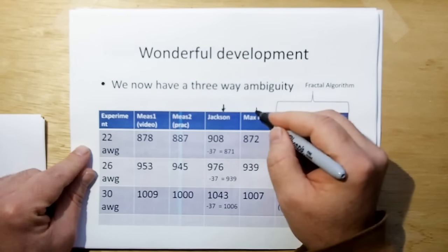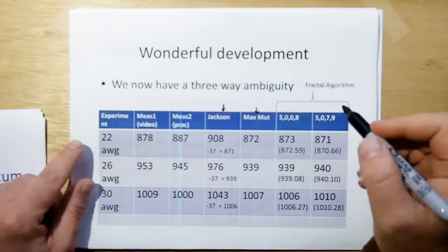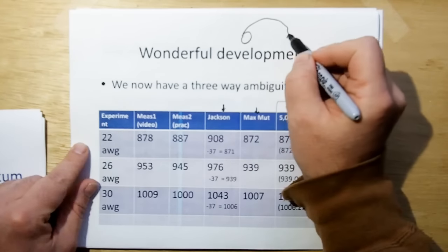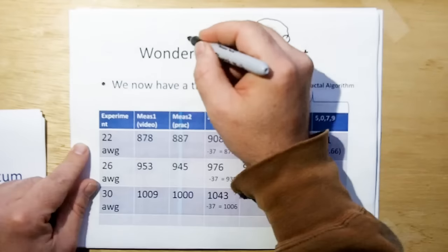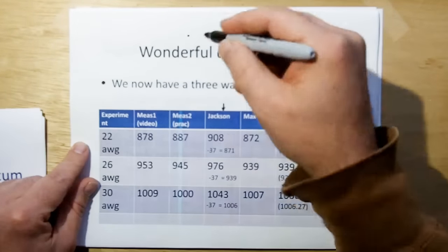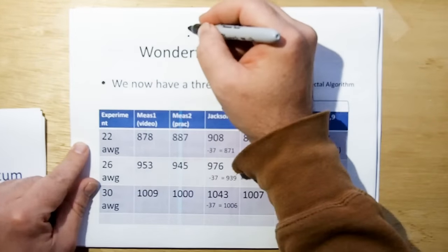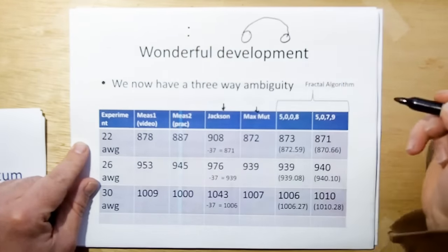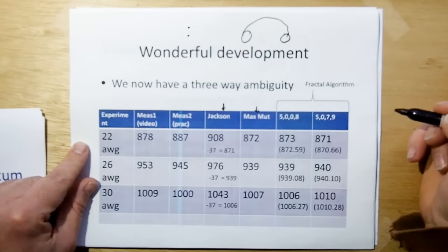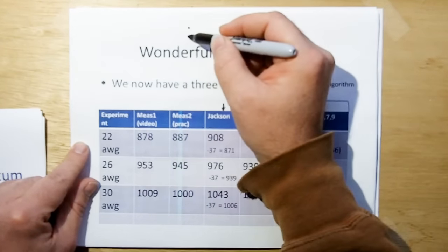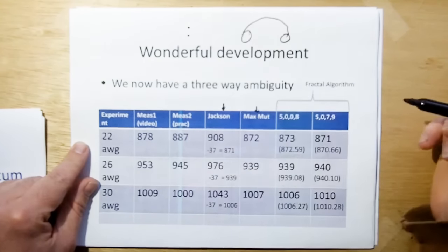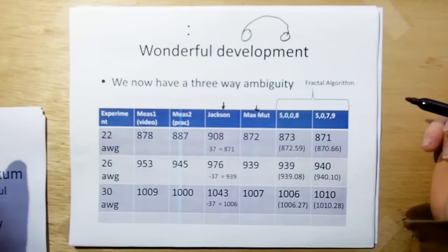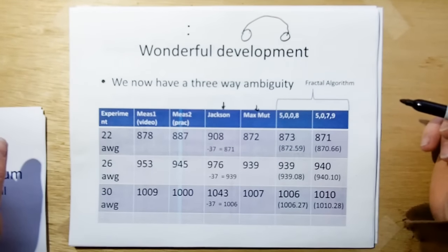And as you recall, Maxwell's mutual inductance is just simply if you have a loop of wire and taking this cross section, you put all the current at the center of the wire and you put a test loop at the edge of the wire, and you compute the mutual inductance between the filament area at the center of the wire to the current through the loop of wire at the edge of the wire, you get a fantastically good result for self-inductance.